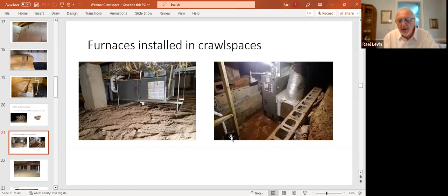In the bottom corner here, we have a sump pump, so we are somewhat protected. But this is, again, an area that has been enclosed below the dirt level in the crawl space. We can see here we have an ejection for a condensate line as well. So they're doing the best things they can, but they have not addressed the water into the crawl space area right here. So that would need to be taken care of.